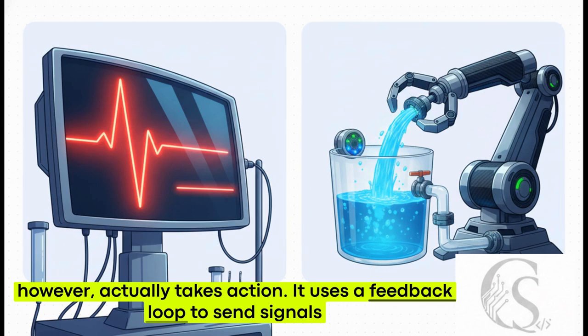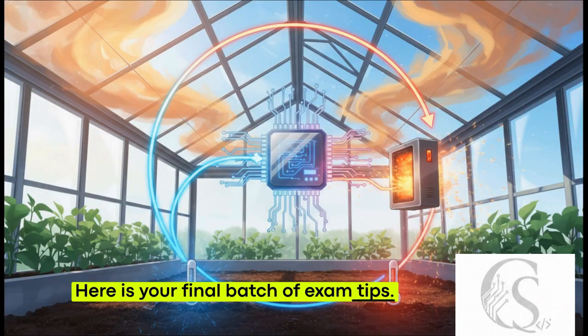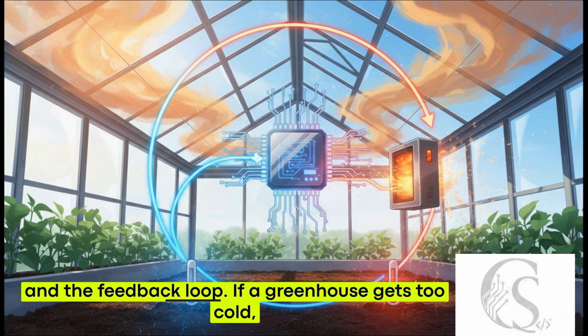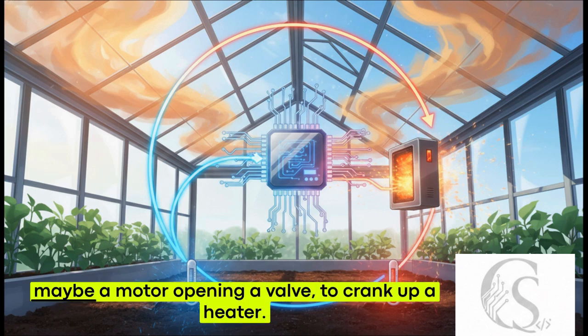It uses a feedback loop to send signals to output devices called actuators. These actuators then change the physical environment. Here is your final batch of exam tips. You really need to master the concept of the actuator and the feedback loop. If a greenhouse gets too cold, a control system doesn't just beep about it. It sends a signal to an actuator, maybe a motor opening a valve to crank up a heater.